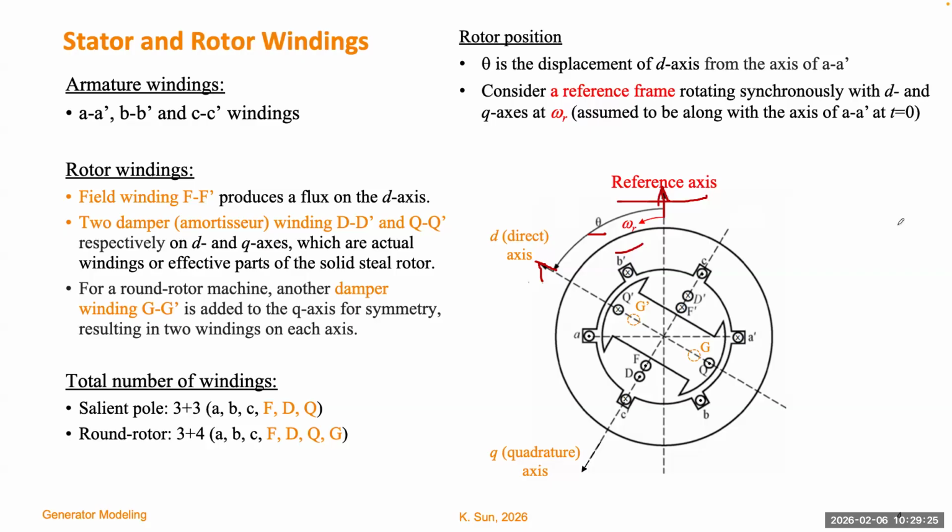So if they stay within a limit, we will see all the generators are in synchronism. If any generator has angle separation growing until it becomes uncontrolled from the reference frame, then we'll see that generator become out of step. So it's very important to define such a revolving reference frame at a common speed, so we can estimate whether each generator can remain stable.